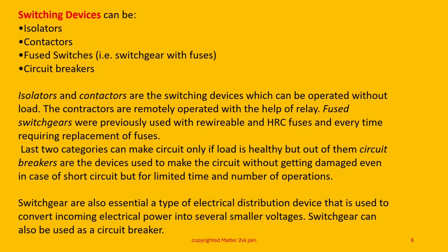Friends, the switching devices can be either isolator or contactors or fuse switches, that is switchgear with fuses, or circuit breakers. Isolator and contactor are the switching devices which can be operated without load.